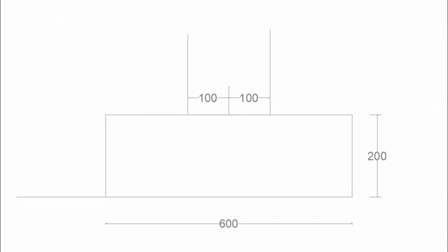So to place the foundation wall, because we've been told the foundation wall is a 200 millimeters stone wall, the best way to do it is to get the center of this, which is half of this 600. At 300 there, you measure 100 on one side and 100 on the other side. Remember, we are using a scale rule, and if you have a scale rule, you just need to check the scale of 1:20, and you will measure directly as has been given.